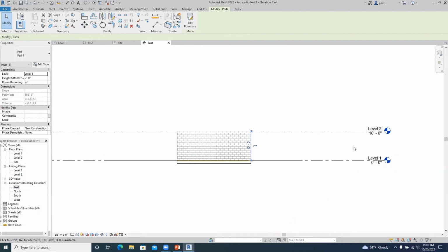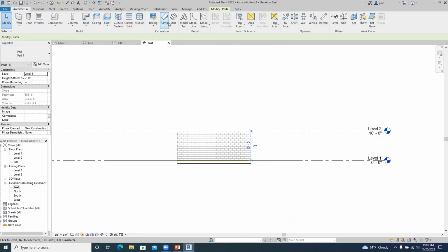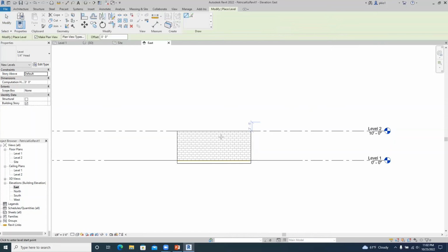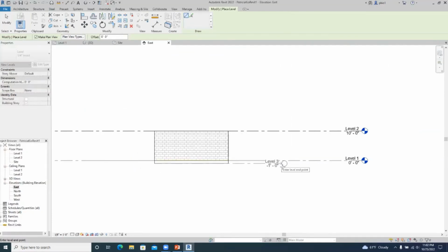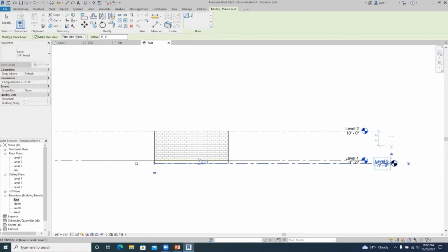Okay, so we have the height of the wall as 10, and then this is the building pad. Then it's stuck in the ground. We want to see it, so we can create another level here, which we use to set the height of things in the drawing. So if we select level here, and then pick it's already on the line tool, so that way we can come and draw at the base of our level. It automatically just calls it level 3.